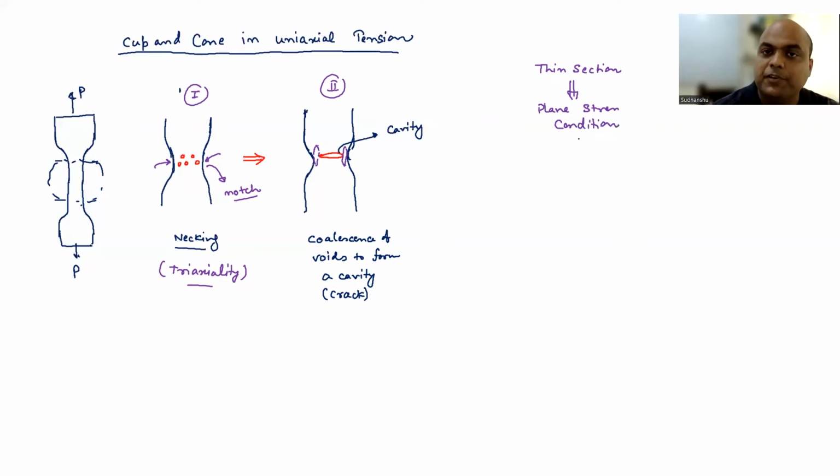Now, if you remember, when we apply the Tresca criterion, this will be in biaxial mode now, right? Biaxial mode, because sigma 3 is going to be 0, right? Now you apply the Tresca criterion, and the yielding in plane stress is similar to the yielding in uniaxial tensile loading.